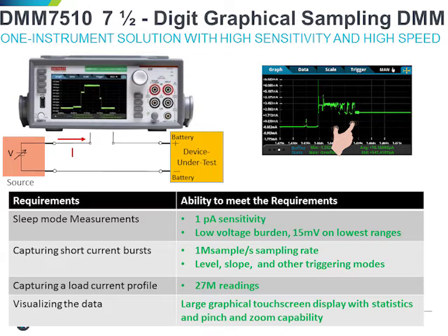In addition to displaying numerical readings, the DMM 7510 has a touch screen graphical display. Waveforms can be plotted, and a pinch and zoom capability allows detailed analysis of a waveform. Thus, you can expand and study the load current bursts in great detail.